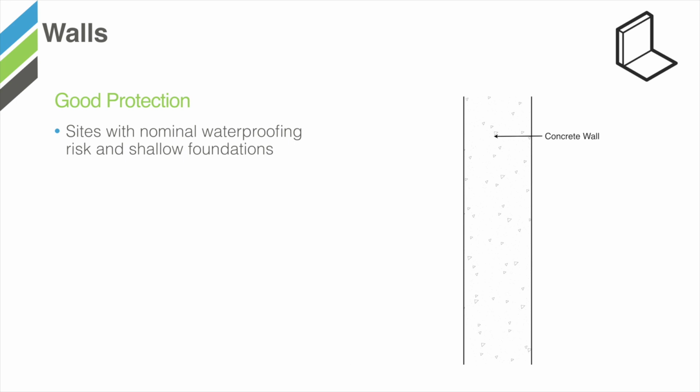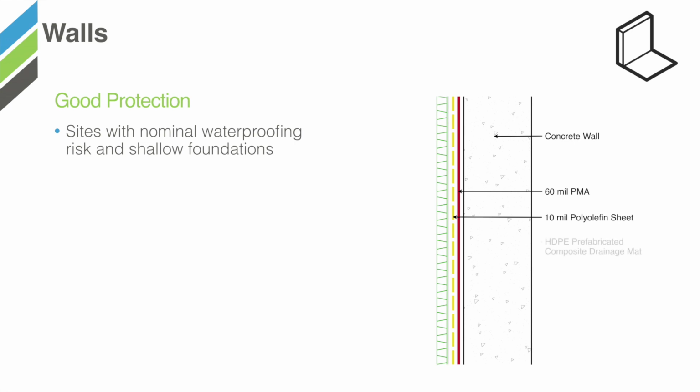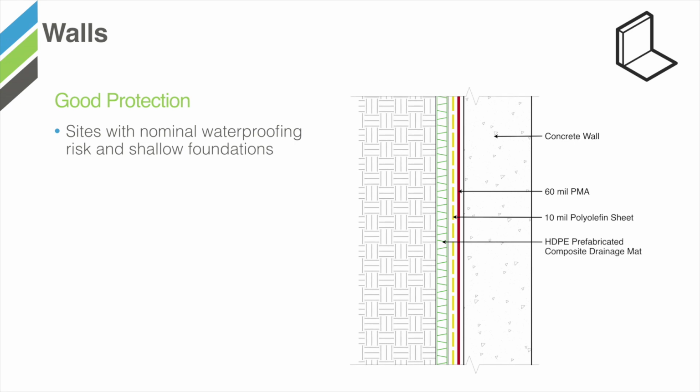After the concrete surface has been properly prepped, a 60 mil polymer-modified asphalt is sprayed directly to the below-grade foundation wall. A mechanical bond is formed between the polymer-modified asphalt and the concrete surface. Then a protection course is applied, followed by a drain mat. The drain mat and the protection course help protect against backfill as it occurs during the construction process.